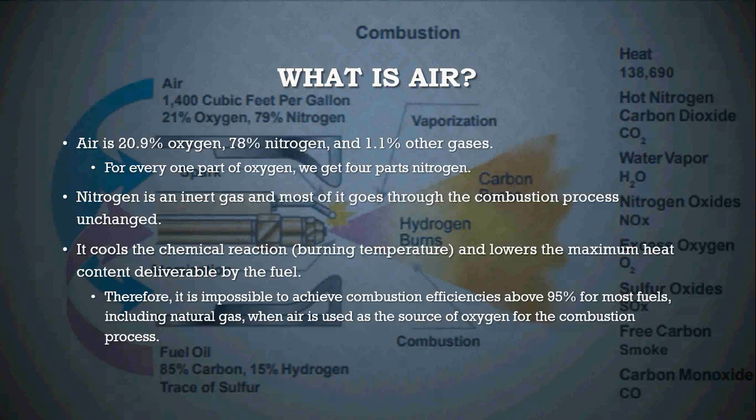Usually a lot of them are about 85%, maybe some are about 90% efficient. That's still 10% of the heat being generated from that equipment going out the chimney. But again, it's our responsibility to understand how the combustion process works in order to get a furnace up to an efficiency rating as high as we possibly can.